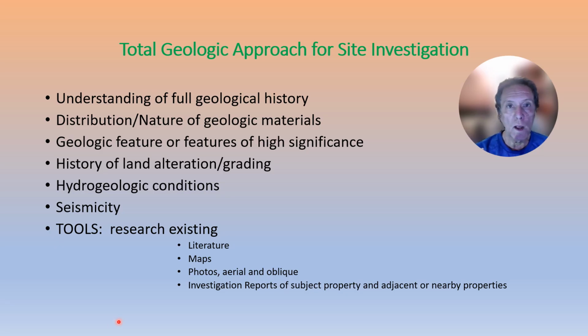So we want to have a total approach for site investigation of a given property, an understanding of the full geologic history of the property, the distribution and the nature of the materials, anything of high significance, as I've mentioned before, such as possibly expansive thick clays or soft, loose, saturated sediments, high significance characteristics that you must account for.